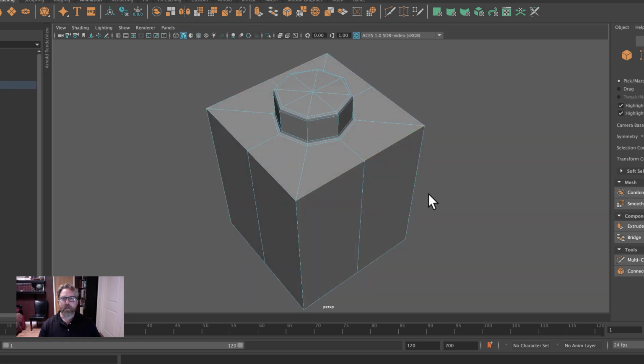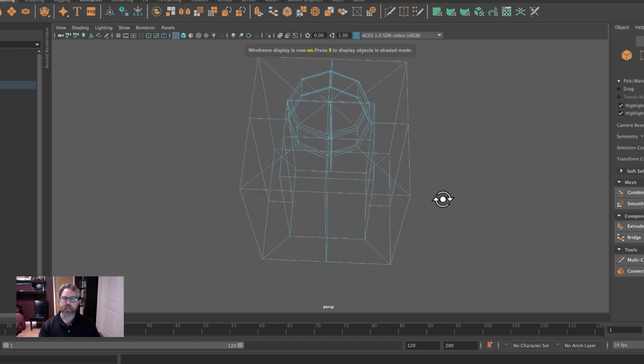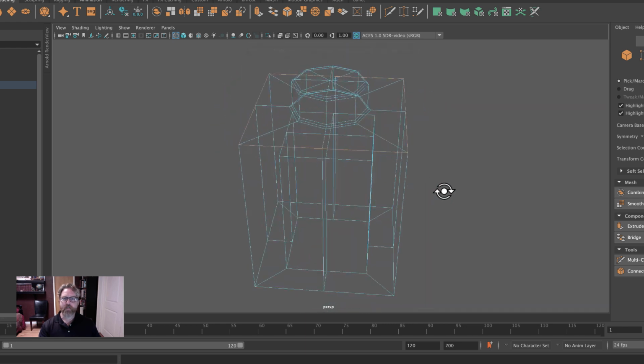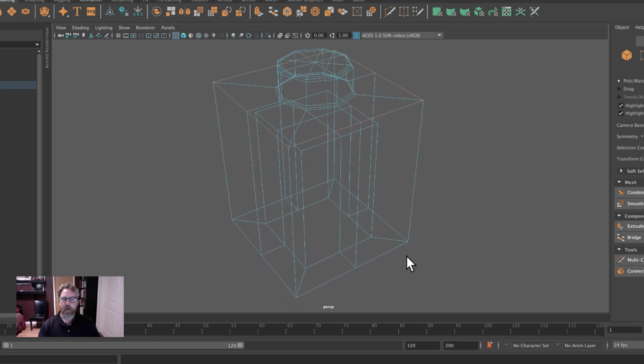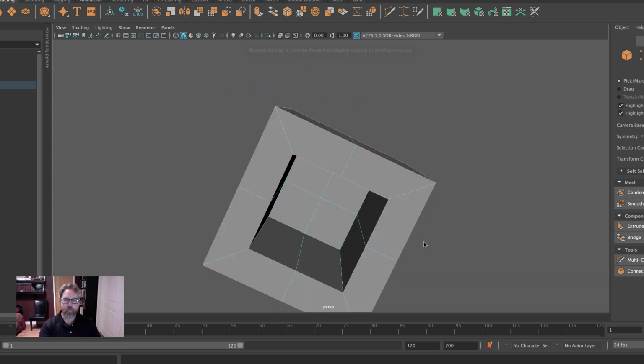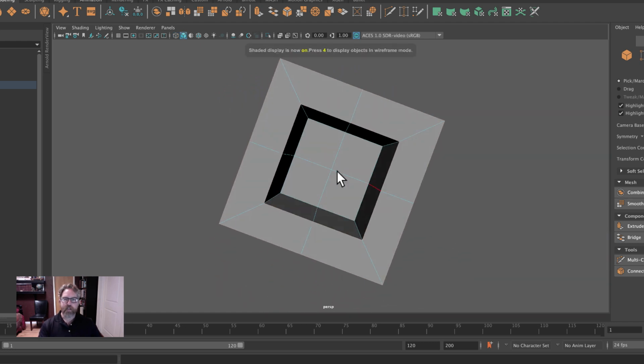I'm going to double click that top edge. So let's just look at that. So that's our first square edge selection on the top. I'll shift double click this edge. So now we have two square edge selections. We'll shift double click the third. So 1, 2, 3 squares. And the interior, we have to select all around. So I'm going to shift double click. That just gave me these two. Shift double click, shift double click, shift double click.